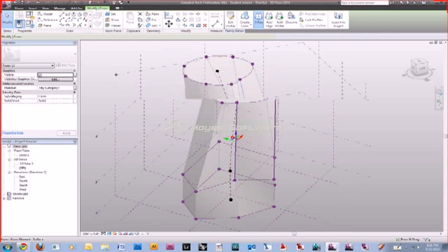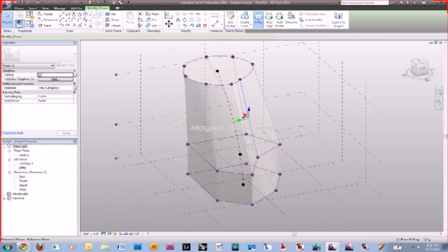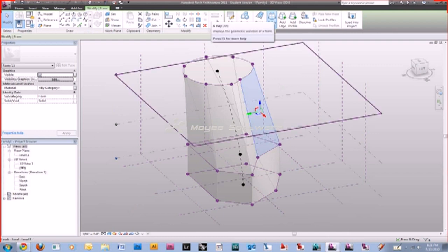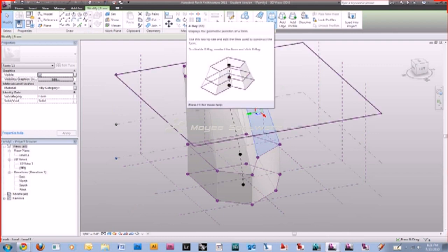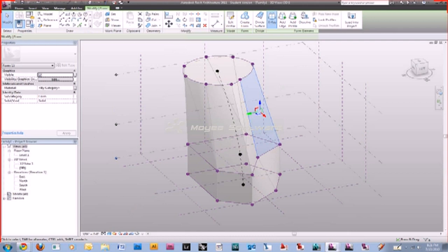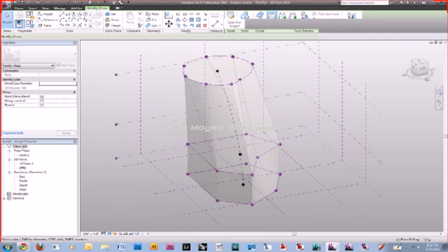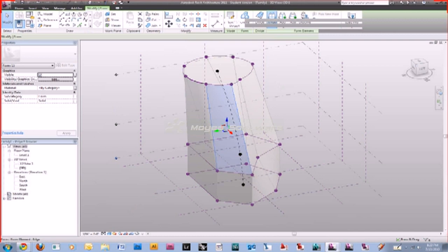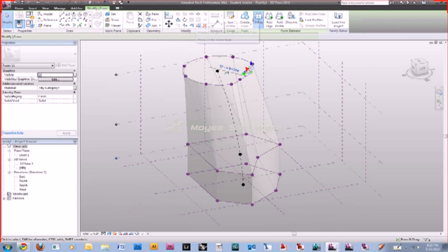All right, so the last tool that's beginner-ish, intermediate-ish, is the dissolve command. Also, before you go to that, make sure you click the X-ray button to get out of X-ray. If you don't, it's going to stay X-rayed all the time while you change stuff. Once you edit things in X-ray mode, get out of X-ray mode. And you can't just escape out of it. You have to hit the X-ray button again.